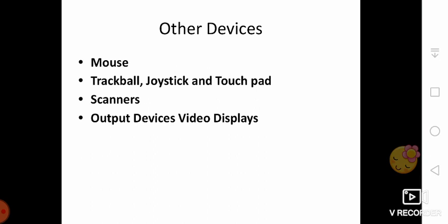The optical mouse shines bright light down onto the desk from the LED mounted on the bottom of the mouse. The light bounces straight back up off the desk into a photo cell also mounted under the mouse a short distance from the LED. The photo cell has a lens in front of it that magnifies the reflected light, so the mouse can respond more precisely to your hand movements. As the mouse is pushed, the pattern of reflected light changes, and the chip inside the mouse uses this to figure out the motion.